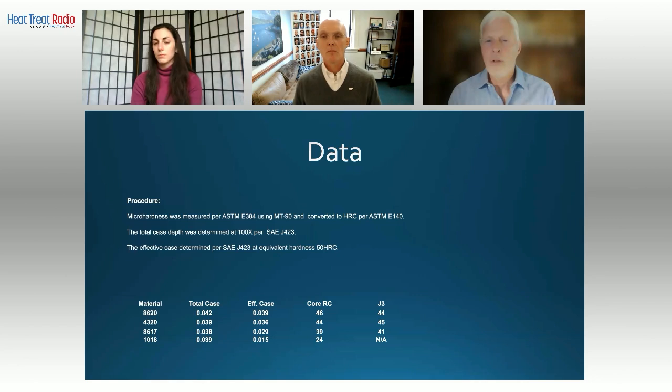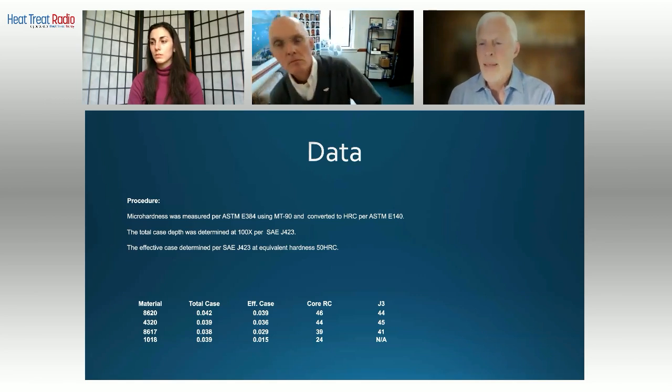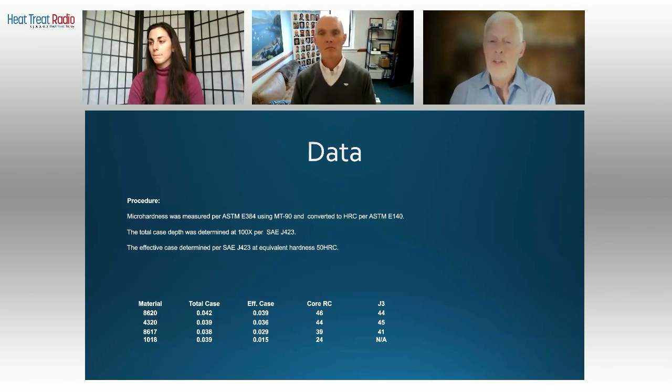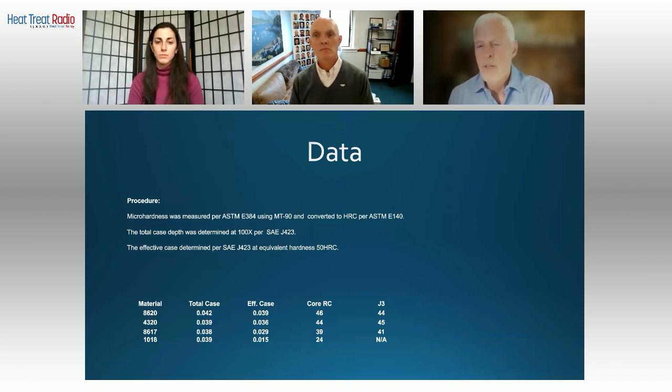So internally, what we say when we're using this data is that we want to be plus or minus 2 points Rockwell C within the steel certified hardenability data. And I can say, again experientially over years, that Gerdau, SDI, Nucor, the domestic sources of SBQ bar, are very consistent in the way that they make this stuff. And this is something that we can depend upon.